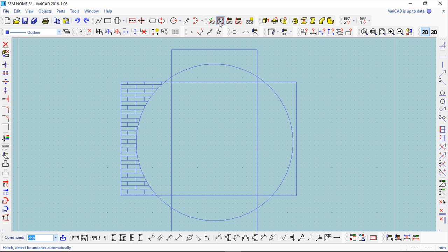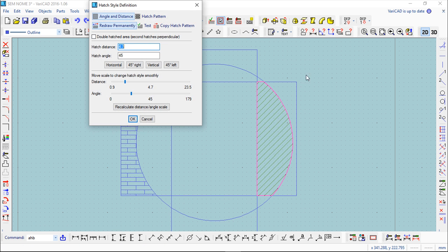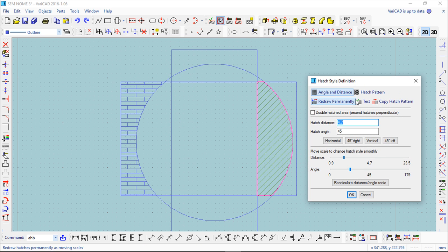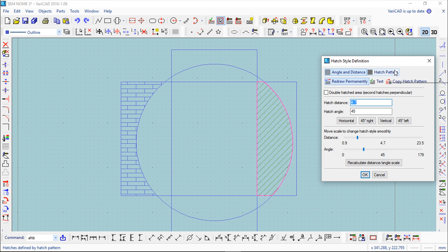Just to show you a little better, because I think it was not so well explained regarding this window. There are a couple of things you can have here, for example, this kind of density. If you put it at the lower extremity, but you still want it more dense, you can say recalculate, and then it will open up to become more dense, and you can go in this direction.